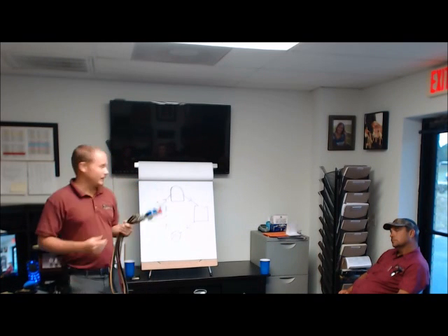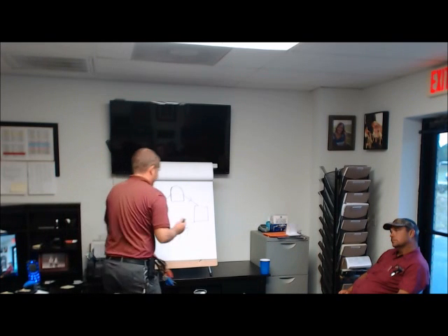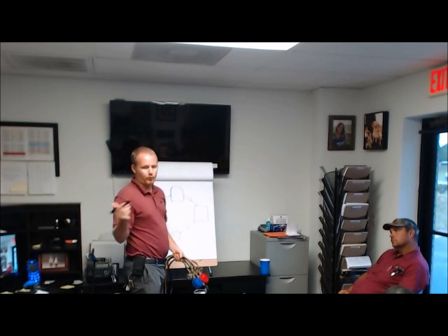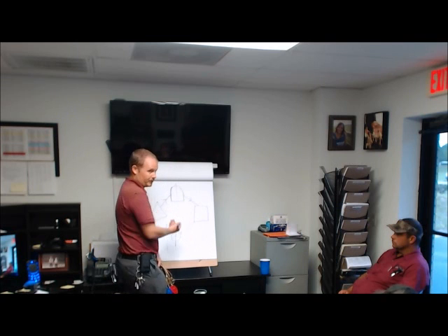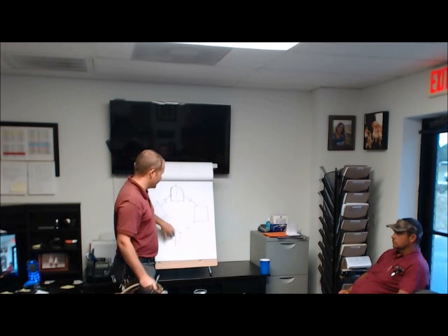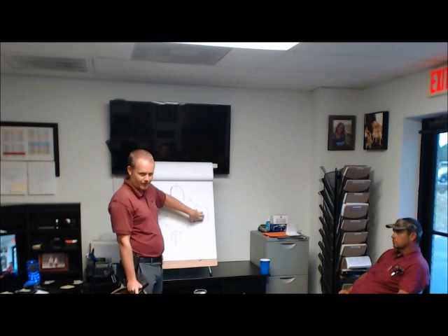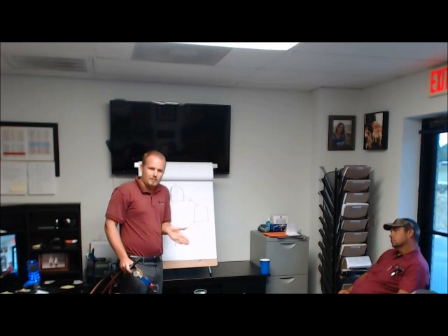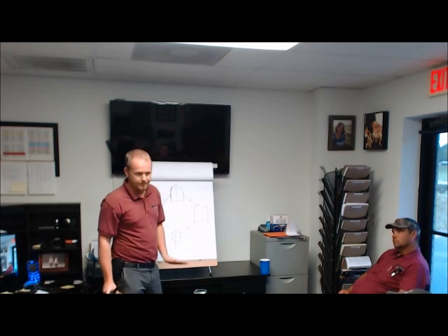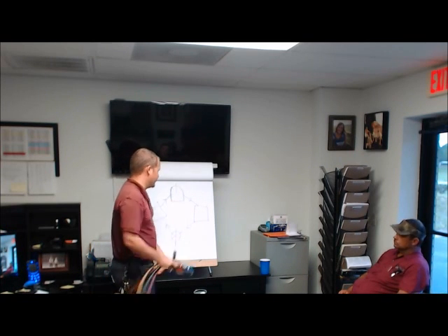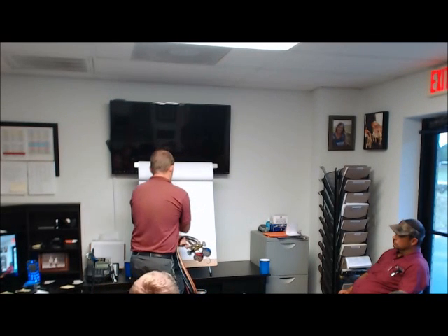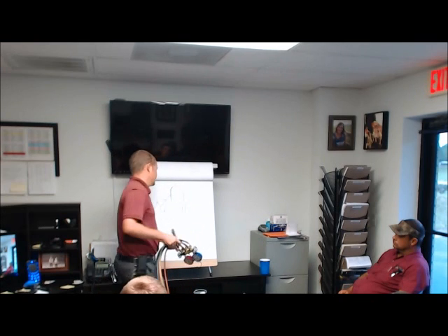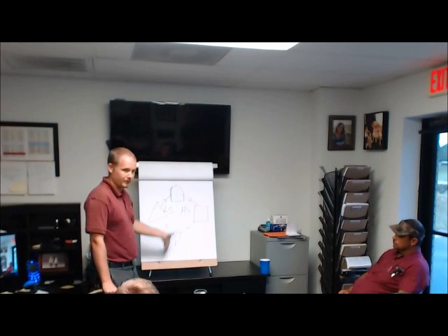So really you can think of it in two different ways. You could describe it two ways and both would be correct. You could describe it the way that Nathan Bishop just did, that it backs up the liquid, which is true, because without your metering device, you don't have adequate pressure over here. In order to have pressure, you have to be building pressure up against something. That's what's causing the pressure difference. Correct. Over here we have the high side of our system, and over here we have the low side of our system. Your compressor and your metering device split those two halves of the system.